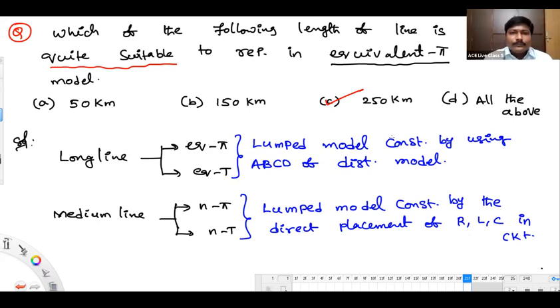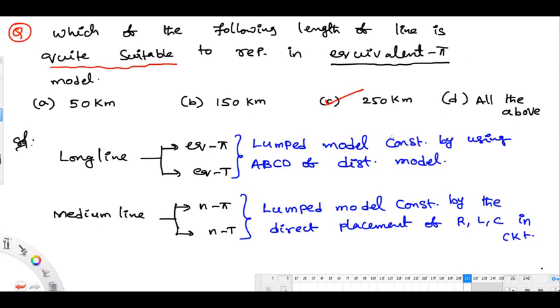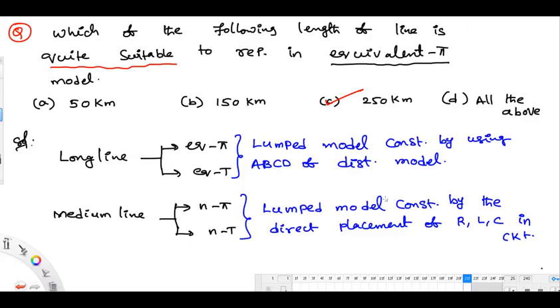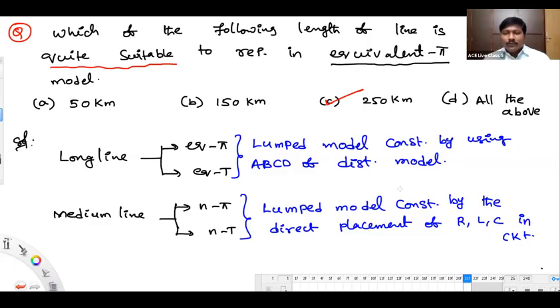Salman Khan. Good morning, sir. Good morning. Tell me, Salman Khan. Sir, we have seen the formula for voltage regulation as no load voltage minus full load voltage. Actually, the exact definition is this: how much rise in the voltage you are going to get after disconnecting the load. That's the original definition of voltage regulation, not no load minus full load by full load.